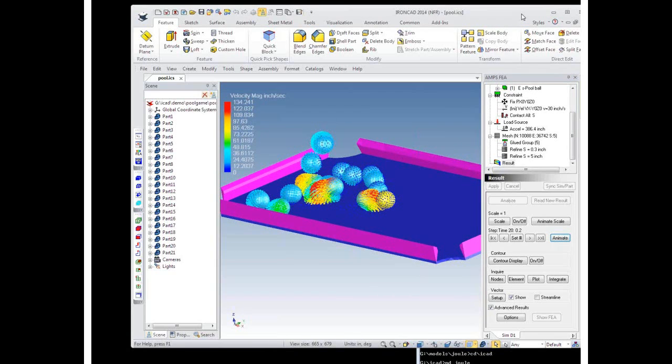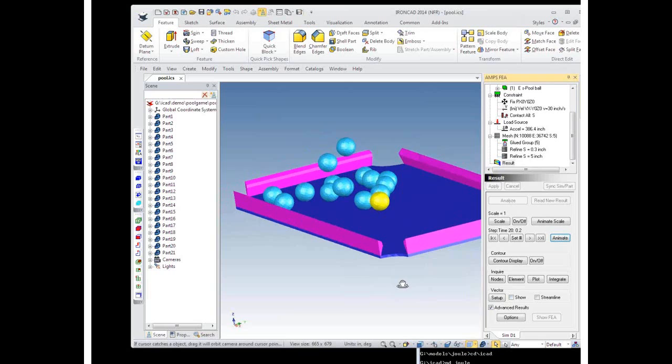Okay, so Gary, I think I'm done. Okay. Just one comment. I just wanted to see if you could highlight the advantages of having that automatically when you have multiple parts. The glue option. I don't know if everybody caught that. When you have that glue option, the mesh, when it's generated, it automatically knows how to continuously mesh between the two parts for you without putting contact.